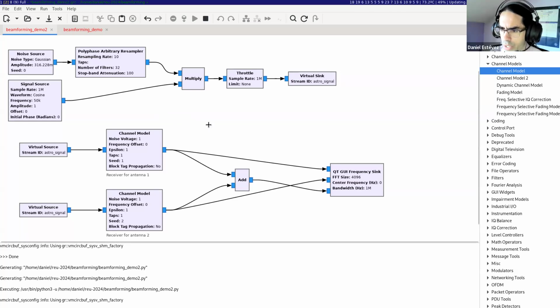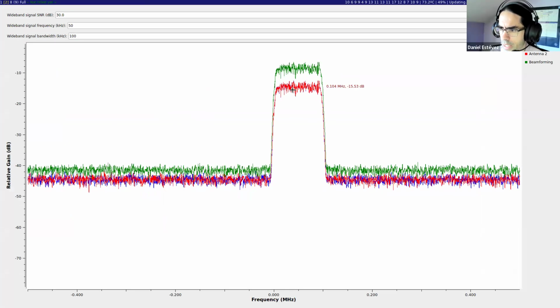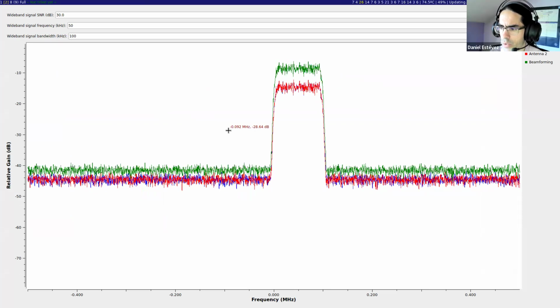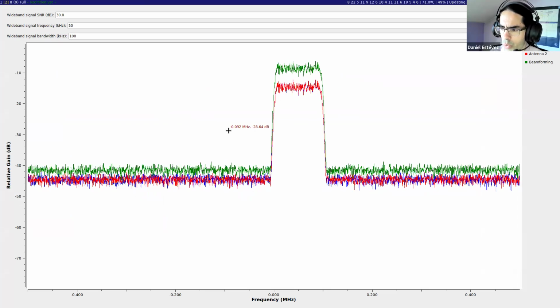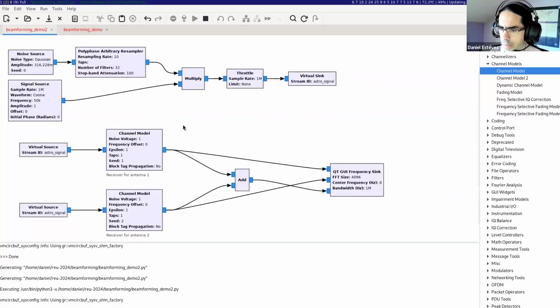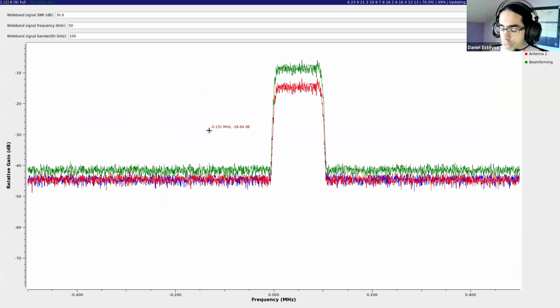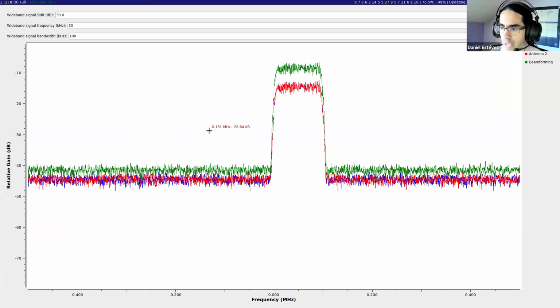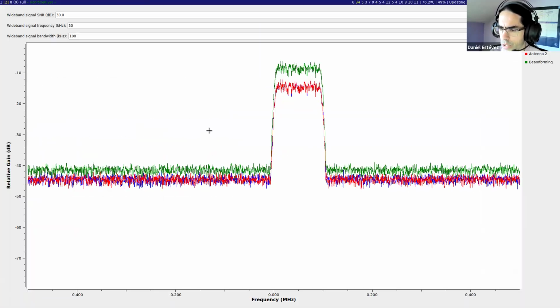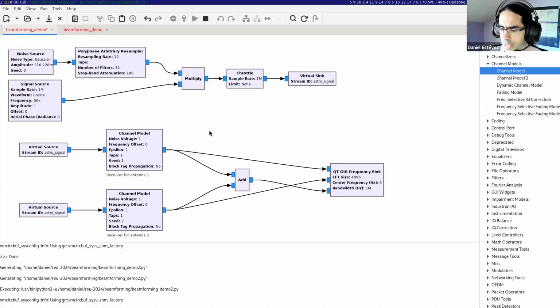So then what happens with the noise? Because, okay, signal gets twice as much amplitude, but if the noise also gets twice as much amplitude, then we are not increasing the SNR because both the signal and noise would grow by a factor of 2 in amplitude. And what happens is that due to the fact that the noise here and here are uncorrelated, we do not get an increase by 2 in the amplitude of the noise. We only get an increase by a factor of square root of 2, and square root of 2 is smaller than 2. So that's what gives the SNR increase.